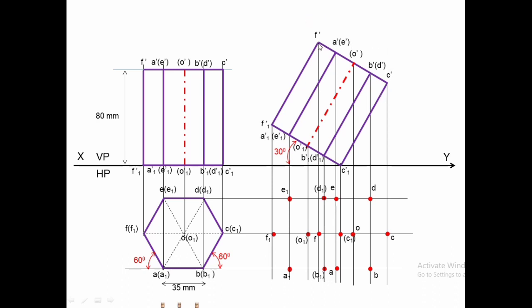Therefore some of the lines will be hidden lines, shown with thick dashes. So now let us draw the very first line. FF1 is the longest line, mark it by thick line here. The top face which is near to the observer is ABCD, mark that in sequence, complete it like this. The second condition of drawing the thick line. The third condition says that you mark the boundaries by thick line. Yes, this completes the outer part.